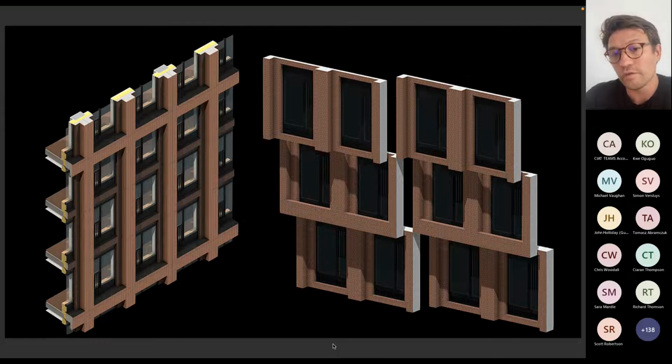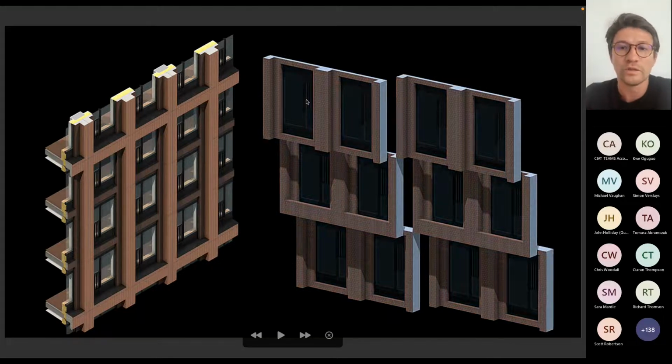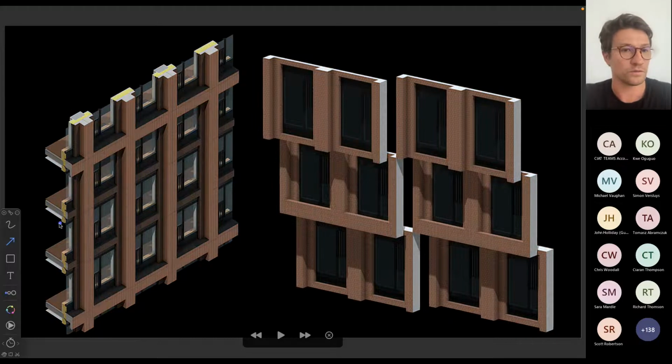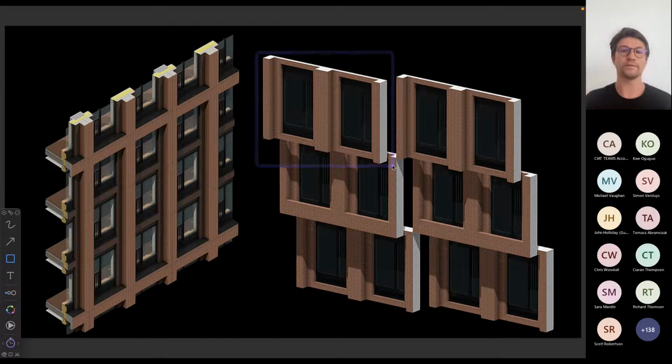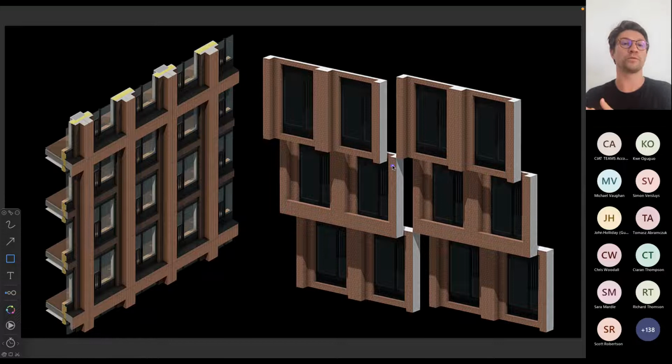So one of the things to bear in mind is that it has to be very, very repetitive, and it has to be a lot of it. The precast concrete facade would not be cost effective for a low-rise building, and not for every mid-rise building, that would not have enough repetition, because precast concrete contractors would want to create one mold and repeat it as many times as possible, and that's how they make the money, and that's how the big project becomes viable.